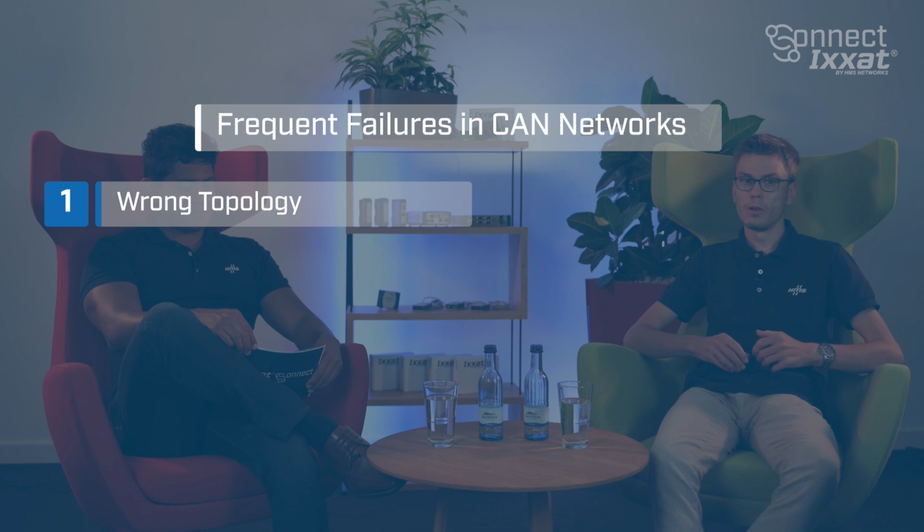Now let's focus on some common physical failures that occur within CAN networks. Tobias, could you give us some introduction on some of these frequent issues? Yeah, for sure, Emilio. One of the major issues is the improper network topology, such as exceeding the maximum bus length or using too long cable stubs, which then disrupt the network's functionality. A poorly designed topology, like having the cable stubs too long or the bus line too long, can lead to signal reflections. These reflections then can cause instability of the network communication.